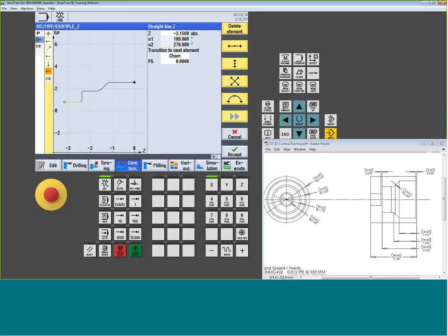So be aware that if I'm stopping in Z, the tool can move further in. Now this was just a slug. There's a hole here. There's all space, so I can let it go there. So in this scenario, I'm not going to pull off in the X. If you do pull off in the X, just be aware she's going to come down to that position even on the finish, and then back off its clearance amount or its retraction amount, and then pull out of the hole. So that's where you want to watch yourself.